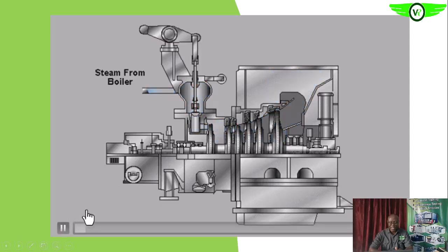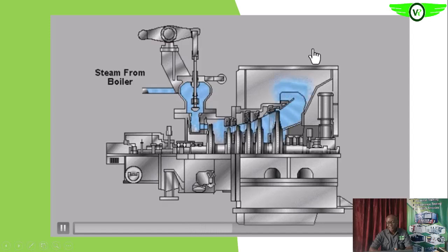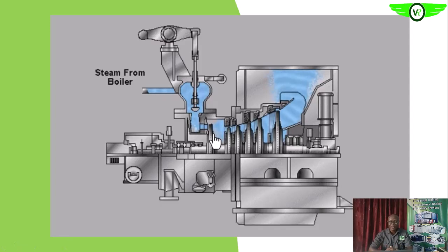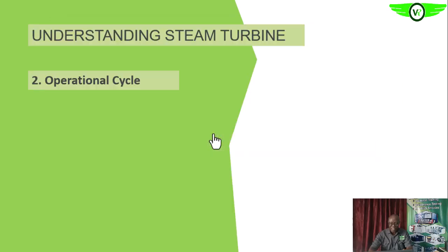So that is what will actually happen in the steam turbine. Okay, then it is exhausted. The steam that you have used the energy from will now be exhausted. Okay, so the exhaust system could be tied to the condensate line or the low pressure steam line, as we said earlier.